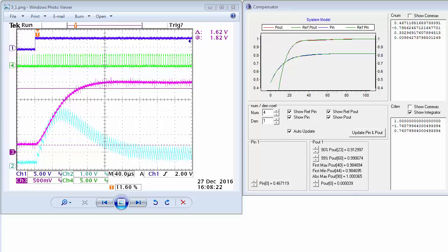The point of continuing beyond 4 and 1 is only to demonstrate possibilities and capability, and accuracy in reproducing the intended plant input and plant output. By now you might be realizing that there are an infinite number of compensator solutions. If the plant input sequence is acceptable, the plant output sequence is acceptable, and the overshoot and oscillation is acceptable, then we're done. All we have to do then is pick a solution that we like. Almost sounds easy, doesn't it?